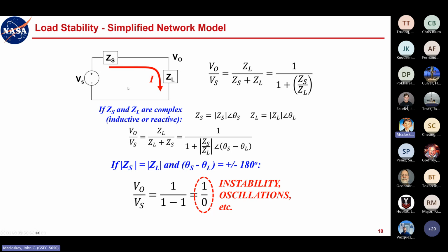I mean, the physical interpretation here is that what the source sees is effectively a 0 impedance, or realistically a very low impedance, right? It sees a net impedance that is very low. All it knows is, what am I seeing right here? And it's seeing the sum of these two impedances, which will look essentially like 0 at this point. So voltage source into 0 impedance will give you infinite current theoretically. And so that's how you get instability and oscillations and so on.